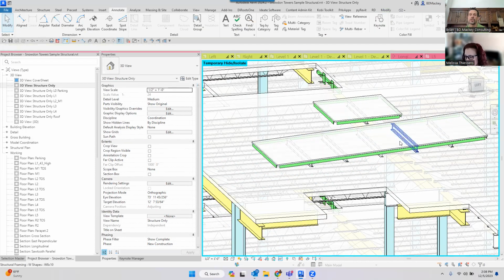It wouldn't matter which direction I was sloping those, or even if I did my beam system angled. By setting it up that way, that's how I control 1,000 beams. Because I use the beam system, I associate those to the beams, regardless of whether those are real beams or what I call reference beams. Those reference beams are associated to columns, real or reference, and then I attach those to the member that needs to be sloped.